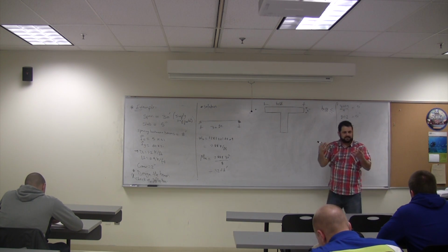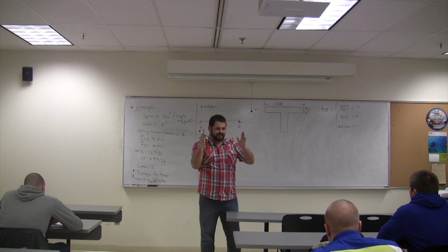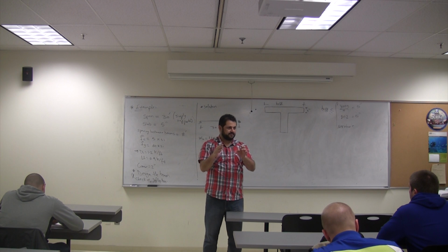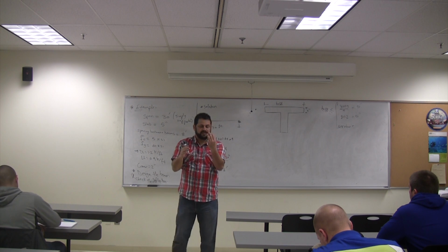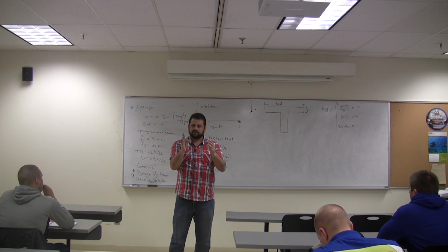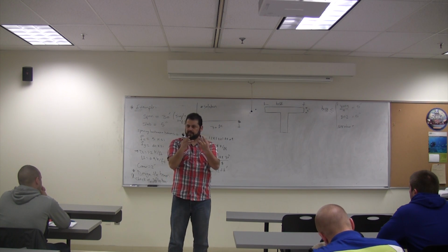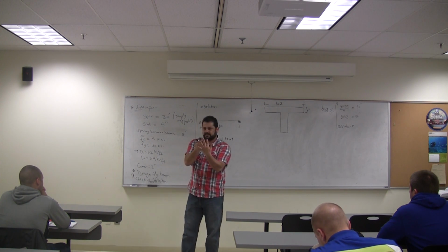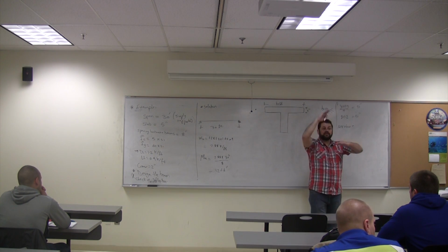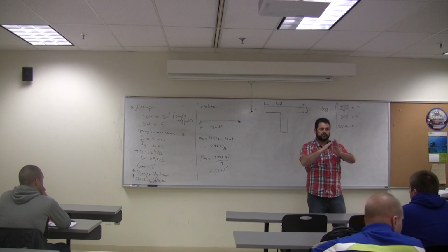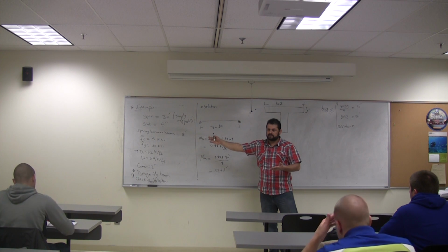Okay, by the way, for guys, it's going to be 8, 10, 12, 14. That number. Look, think about it. If you have 8, you can accommodate, barely you can accommodate 3 bars. In terms of number 9, you will not be able to accommodate them. Because if you take 2 inch to cover side, that's 8 minus 4, 4 left, right? That's the center spacing. So if you have 3 bars, it would be really hard. So usually 8, 10, 12. If you have a limitation on the depth, it may go way big because your depth is limited. Here I'm not putting anything, so we are free to design any depth we want, right?